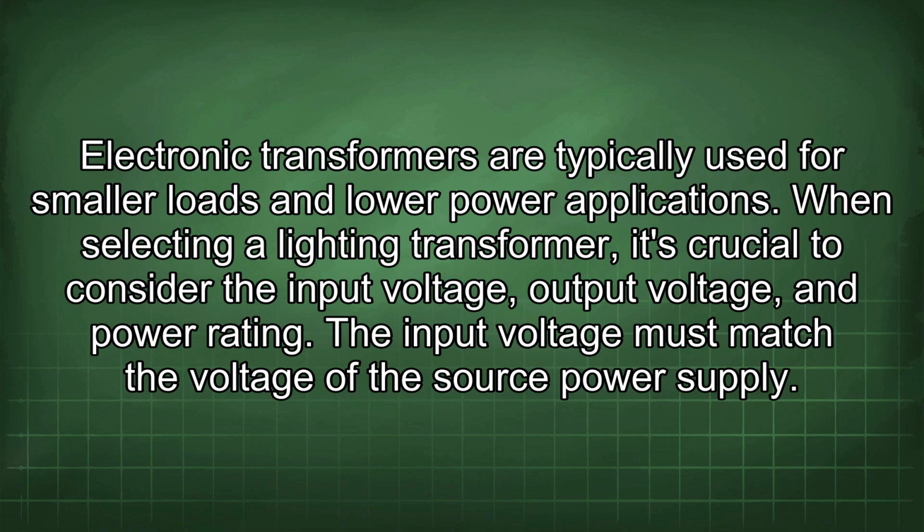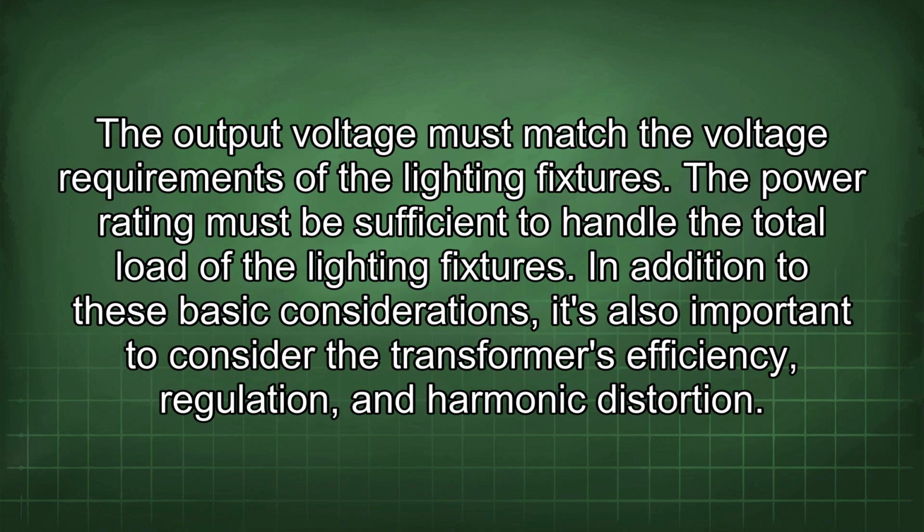When selecting a lighting transformer, it's crucial to consider the input voltage, output voltage, and power rating. The input voltage must match the voltage of the source power supply. The output voltage must match the voltage requirements of the lighting fixtures. The power rating must be sufficient to handle the total load of the lighting fixtures.